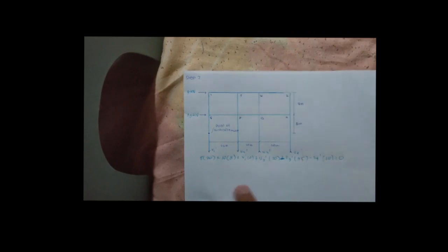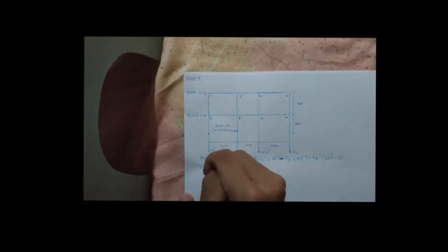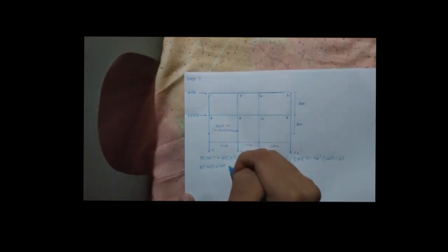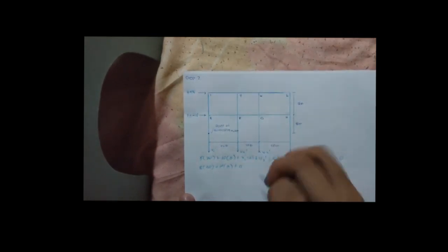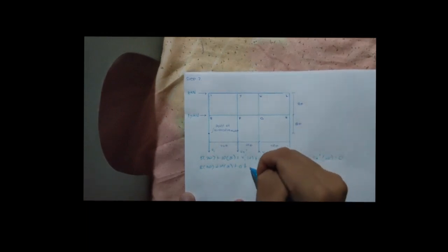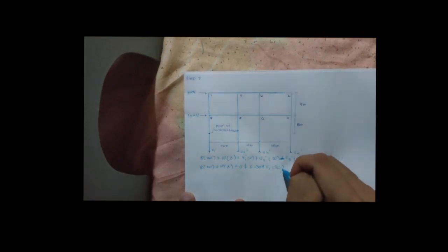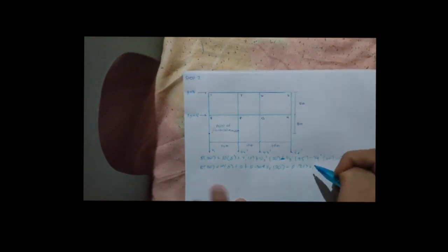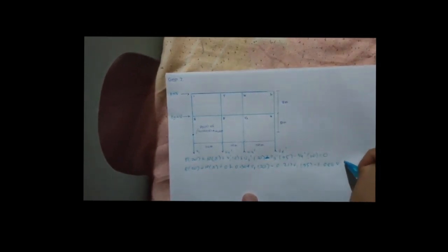Then input. I forgot that we already have the values of V2, V3, V4 that we got, which we can just input. 20 plus 10 times 8 plus 0, since it is times 0, plus 0.304 V1 times the distance 20 minus 0.217 V1 times 35 minus 1.086 V1 times 60 equals 0.